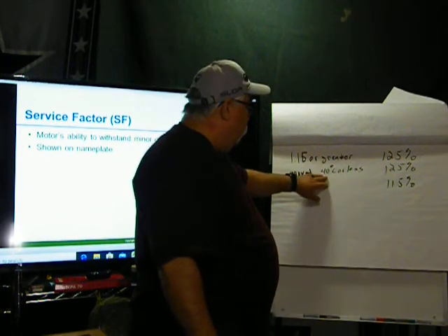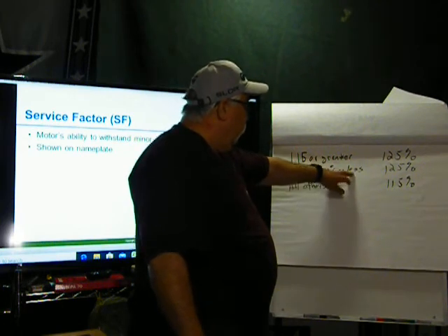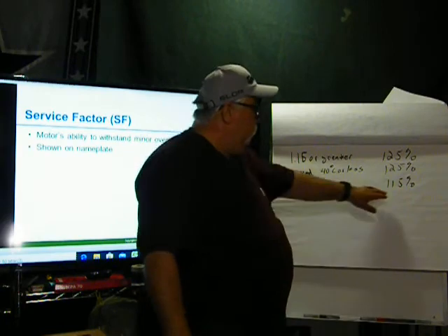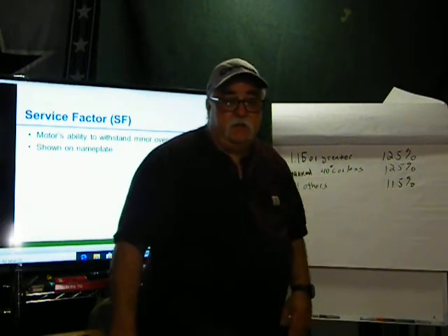If it's marked 40 degrees C or less, use 125%. And all other motors are at 115%.